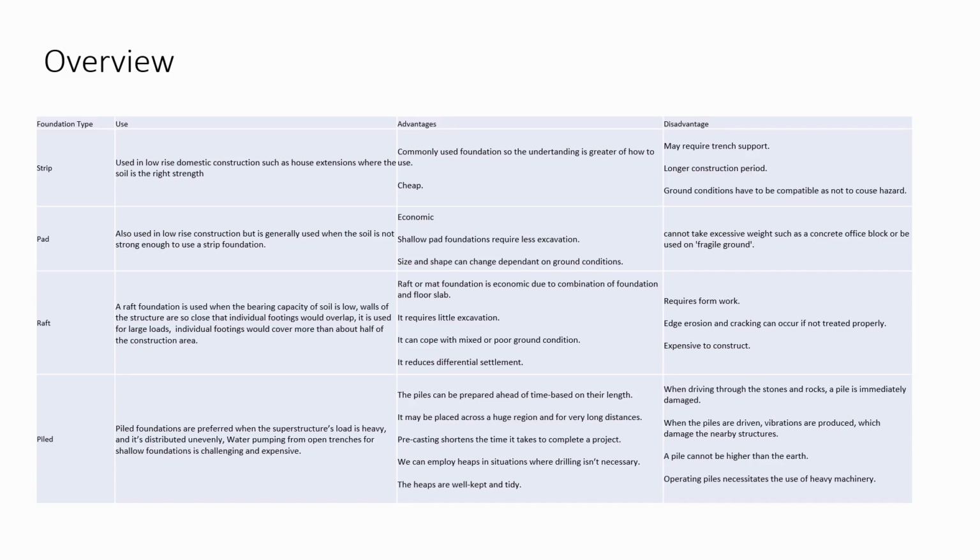A pad foundation is economic. Shallow pad foundations require less excavation, and the size and shape can change depending on the ground conditions. But the disadvantage is it cannot take excessive weight, such as a concrete office block, or be used on fragile ground, so it's not suitable for this project.